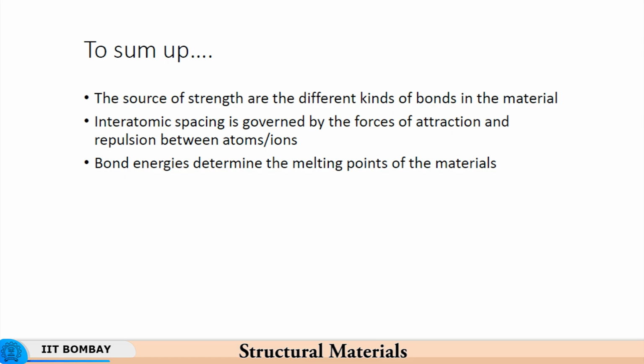And then you have the so-called elastic deformation if the force is sufficiently small, because the atoms change their position, go away from the mean positions temporarily, and then come back to their mean position immediately as the load is released. So this is the source of elastic deformation as far as an aggregate goes. We see the elastic deformation on a macroscopic scale, whereas at the individual atomic level, the change in the interatomic separation is virtually impossible or extremely difficult to measure.